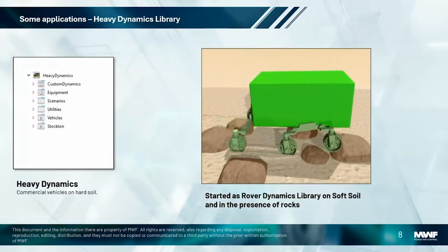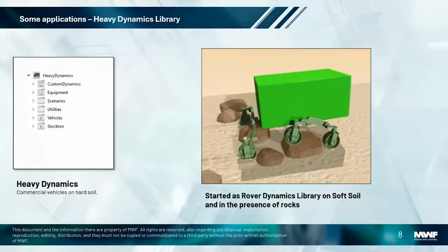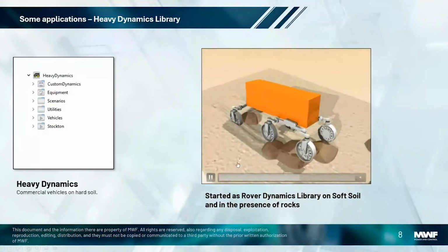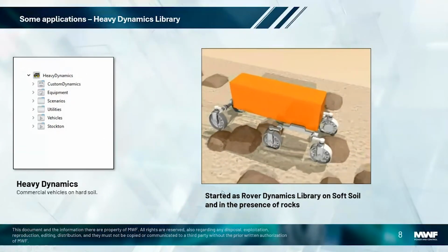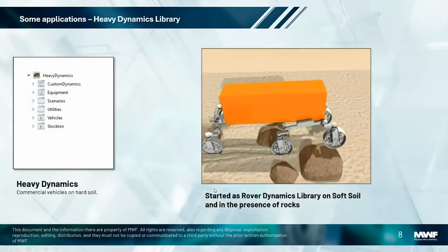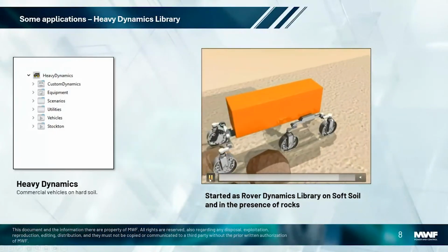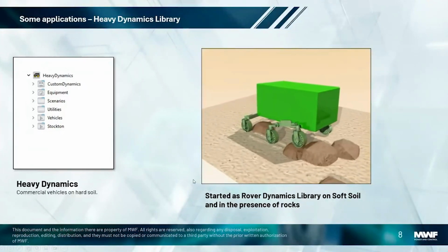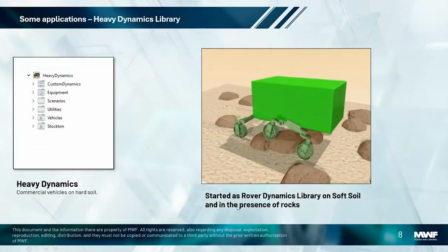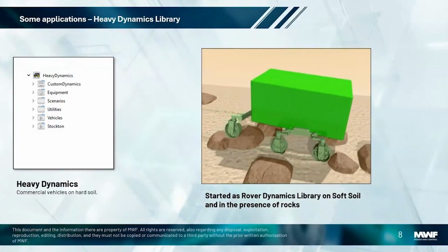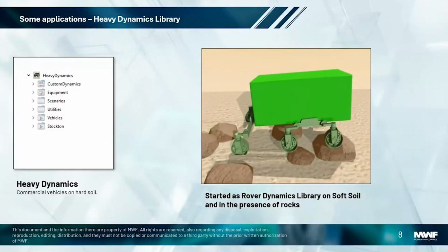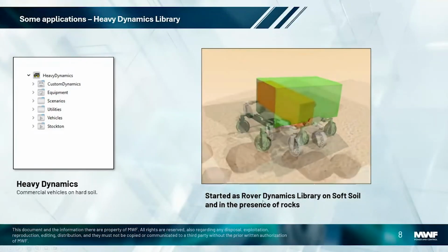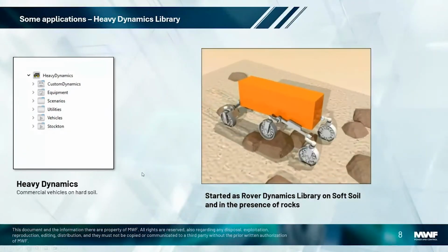And as you can see, it is able to reproduce the trafficability of a planetary exploration rover with many wheels in contact with soft soil, in contact with many stones at the same time, producing tracks on sand, different types of sand, etc. Both sinkage and slippage, both lateral and longitudinal, can be modeled and simulated in this library.